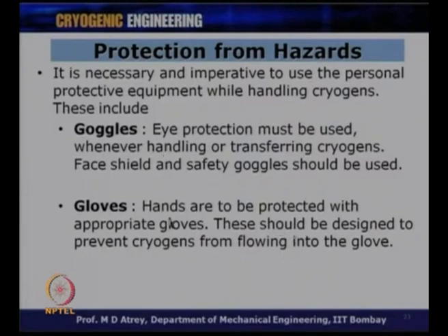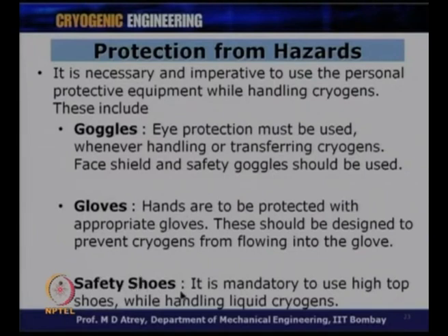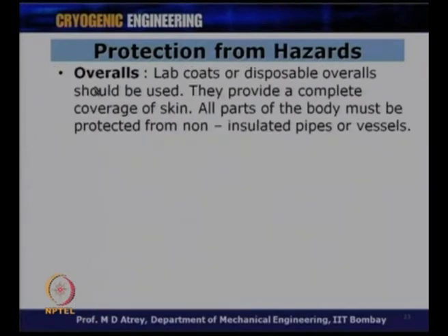So, goggles, gloves, safety shoes, for your legs. It is mandatory to use high top shoes while handling liquid cryogens. So, they are important for your face, your hands, your legs. Similarly, you should have overalls. Lab coats or disposable overalls should be used. So, the entire body should be covered with some kind of gown or coat.